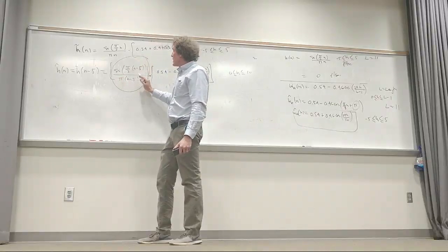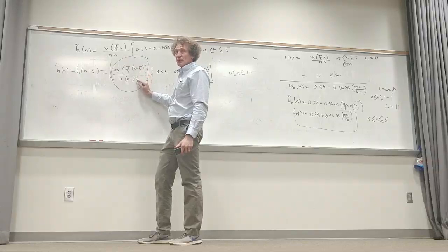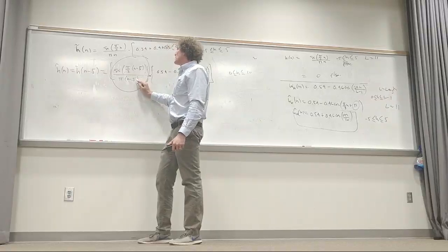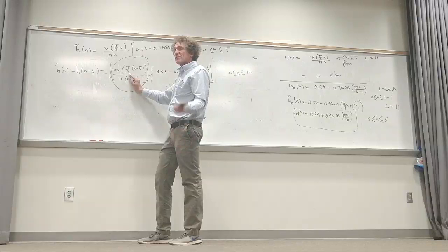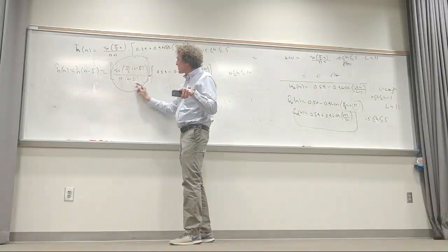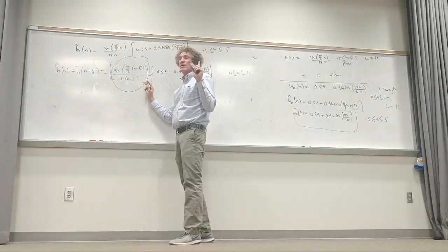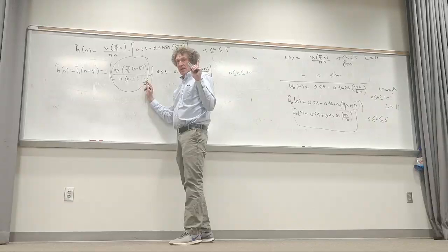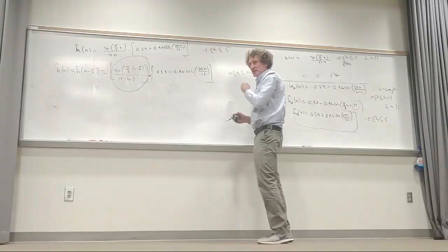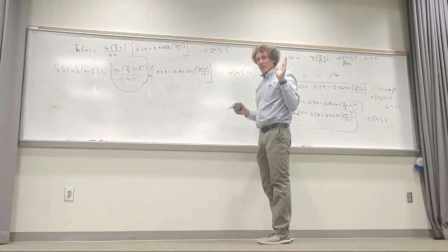Now you have to evaluate this using L'Hopital's rule. Take the derivative of the top, the derivative of the bottom, and evaluate that at the singularity. In truth, the only thing you have to bring out is a value of 1/2. So you have to define the filter response at n equals 5. This part of the filter response has a value of simply 1/2. Understand, class? Everybody with me on that? You don't use this. At n equals 5, that's 1/2 times this. Got it, class? And that's important.